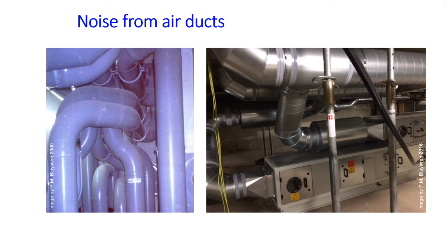When air is distributed through the ducts, depending on the air velocity in the duct, noise can be created, the so-called rustle of air. The smaller the diameter, the higher the velocity with the same airflow rate, the higher the sound level. Additionally, change of duct diameter along the way or direction of the airflow can cause a sound effect.